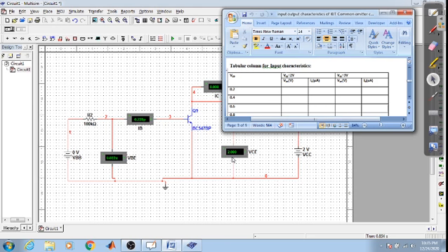You set VCE equals what? 2 volts. Now what we need to do? We need to vary VBB. You need to vary VBB and measure VBE, this voltage, and IB, this. Okay, IB, this has to be noted down. Okay, so your VCE is 2 volts, which is already being set.